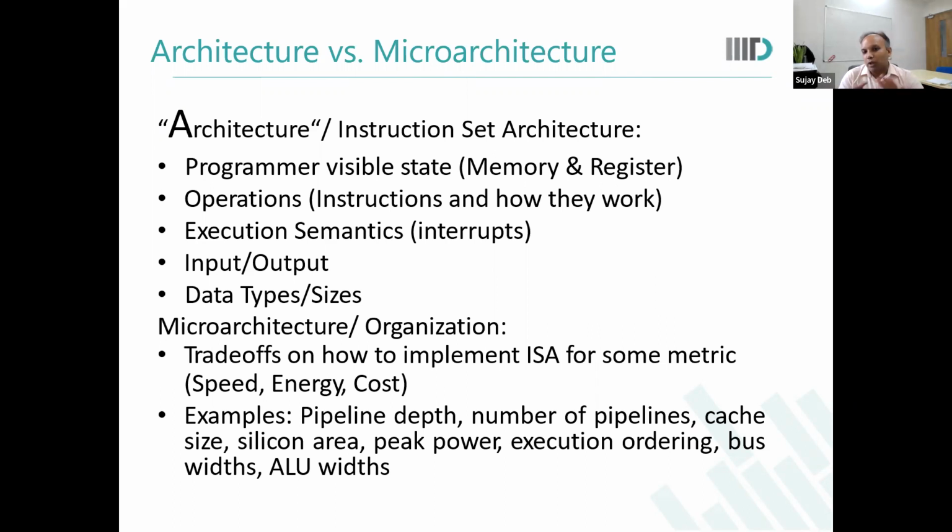So basically one step is you model the system, and for modeling you can use SystemC and see how the performance will change for your different design decisions. The other thing is, if you want to actually implement NoC, then you have to generate the RTL, and we have worked in both directions.